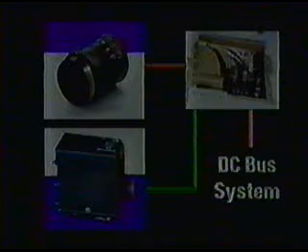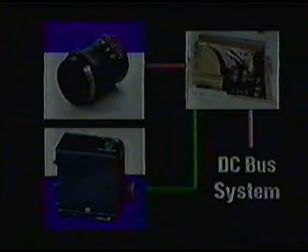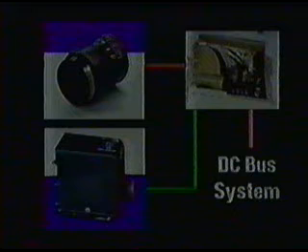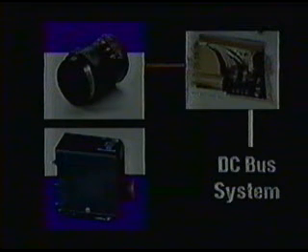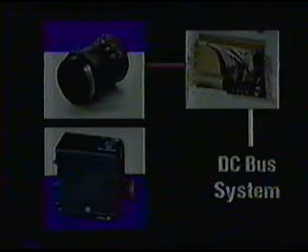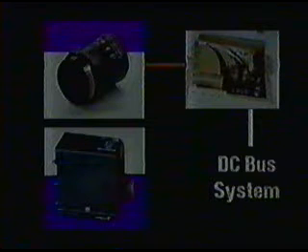Working with the other circuits within the generator control unit, the automatic line contactor function will open the generator relay and disconnect the generator from the aircraft's wiring during any abnormal condition. This circuit will not allow the generator relay to close if any abnormality is sensed in the generator's output.